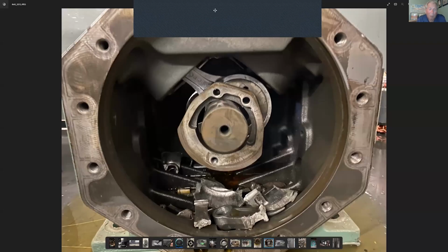Since I kind of started, that's where we were at when I got in the trade. And there's other things that we did or didn't do right back in them days. But loss of oil was always considered to be an issue. I think what's taken that over, and I don't want to skip over loss of oil, but contamination is becoming greater and greater as we've moved to more HFC refrigerants, POE oil. Those things have been a problem for certain too.